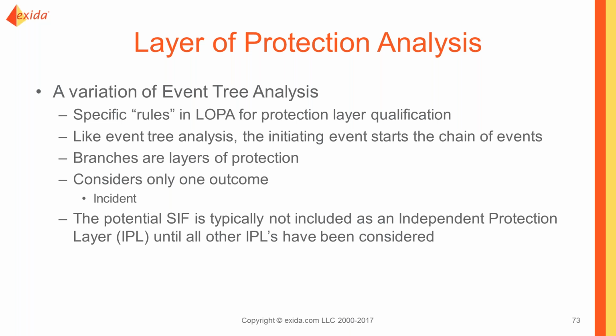Now, also, when we look specifically at 62061, it talks about the SIL determination and references the annex in the back, but it also references Part 5 of IEC 61508 to say you can look there for other methodologies. So when we look into 61508 and other standards, we're going to find maybe a little more robust SIL determination methodology.